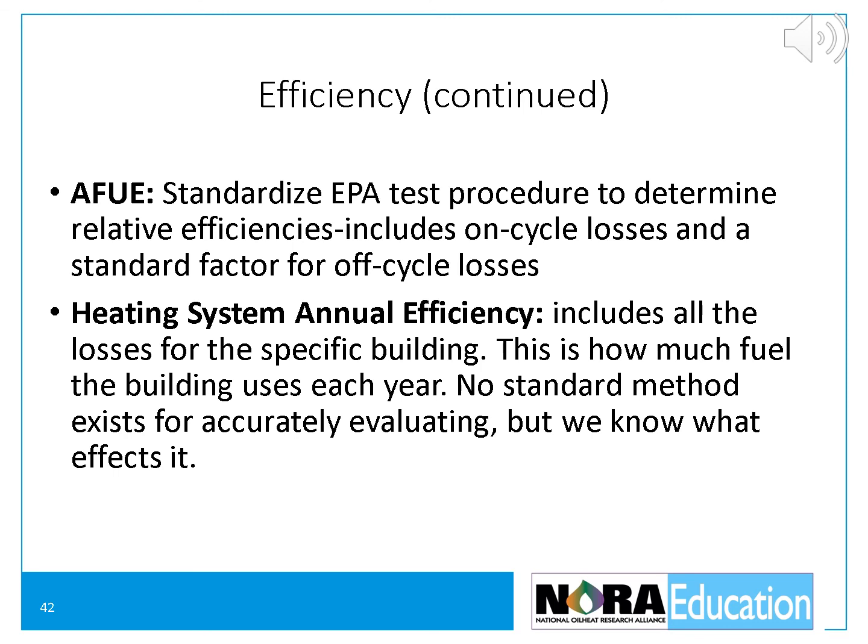It is not intended to measure heating system efficiency, which includes heat losses that vary from building to building. The test procedure approximates on-cycle heat loss and cool-down characteristics, and then calculates off-cycle losses and infiltration losses for standard conditions. There are many real-world cases where off-cycle and infiltration losses are significantly different than those predicted by AFUE.